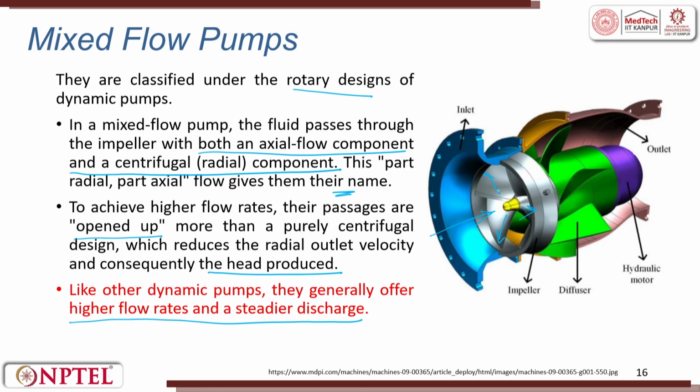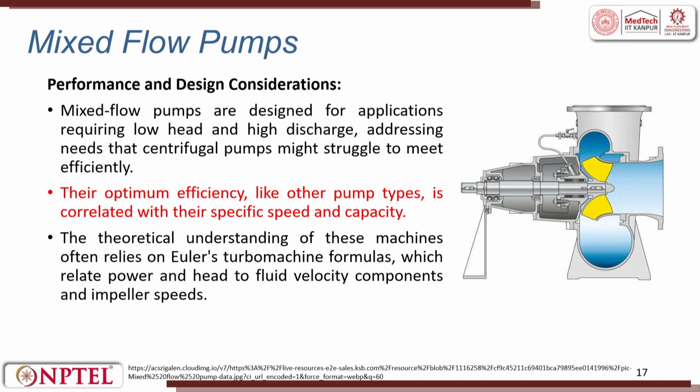So, here it is, the inlet is given through this, and then this is an impeller which rotates. Here is a diffuser, which tries to change the pressure, and then it goes to a hydraulic motor, and here is an outlet. So, mixed flow pumps are used. The performance and the design considerations for a mixed flow pump.